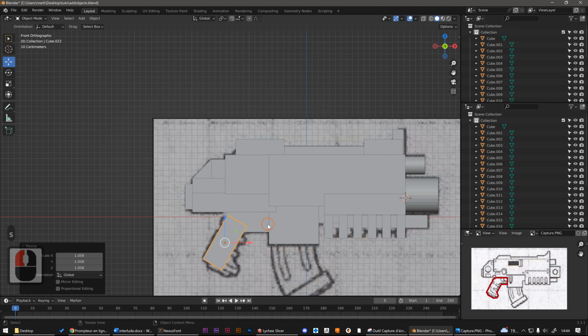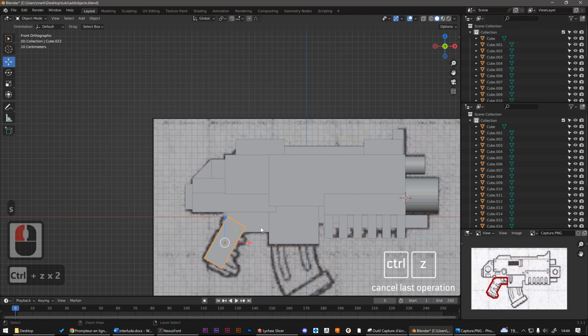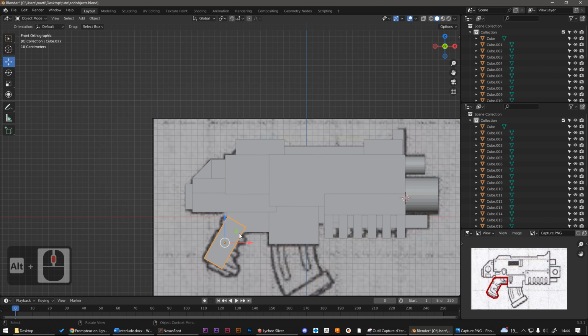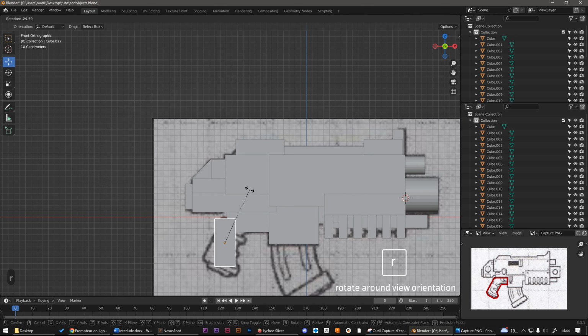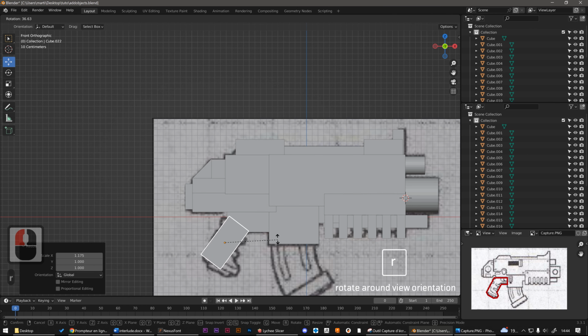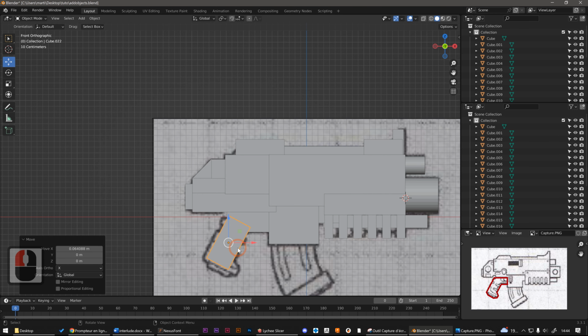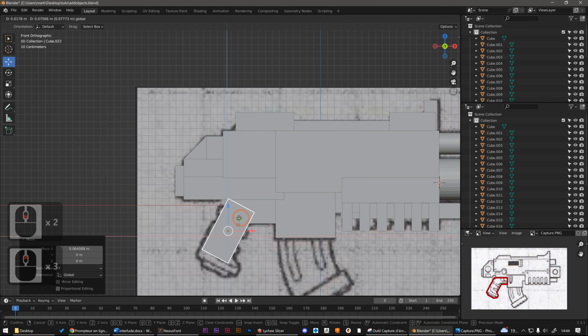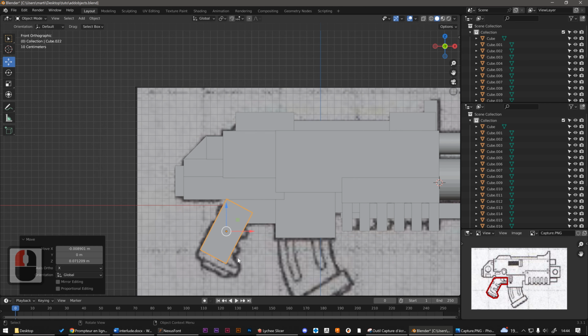But to adjust the scale along the X and Z axis we are a little annoyed, because since we have made a rotation, our object is no longer aligned with the global axis. We will soon see how to use the object's axis orientation, but for now, we are going to cancel the rotation. With another rotation, I am going to get back to where we were before. Then we can scale the object along the X-axis, and there I redo my rotation, G key to move, and that's it. And to be a little bit closer to the drawing, we're just going to do this part.